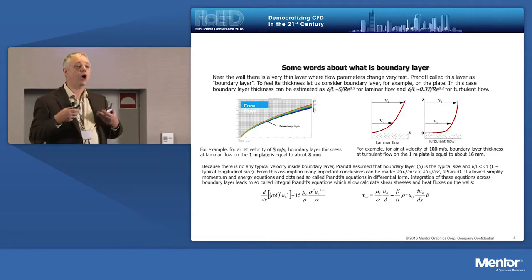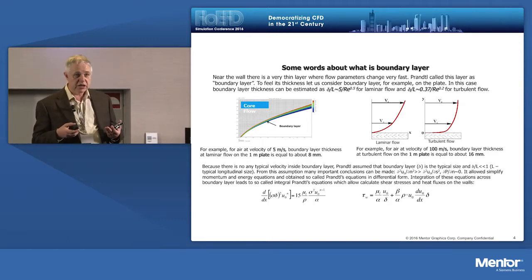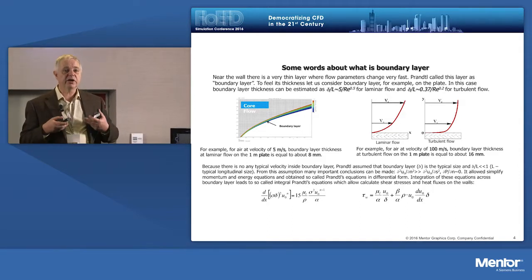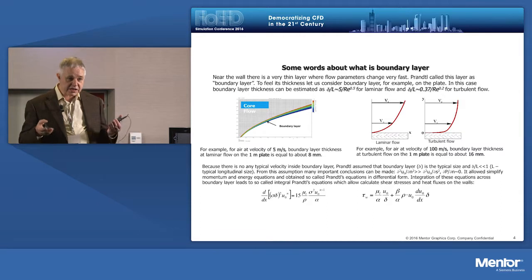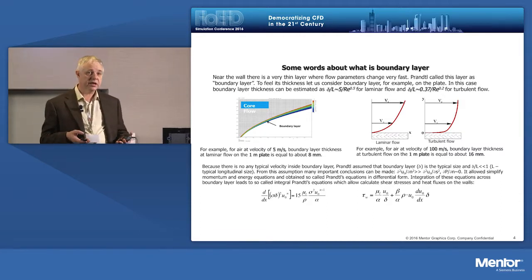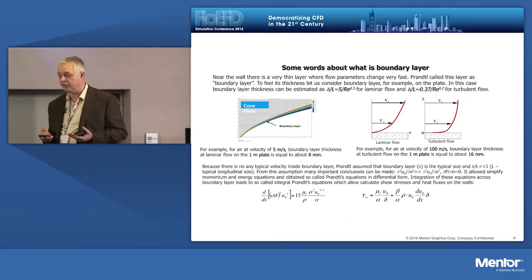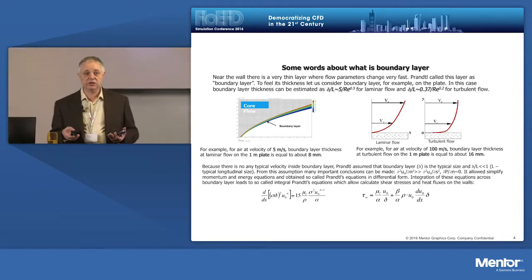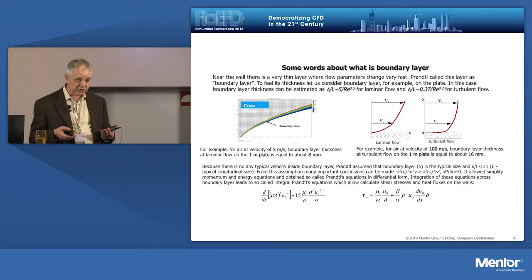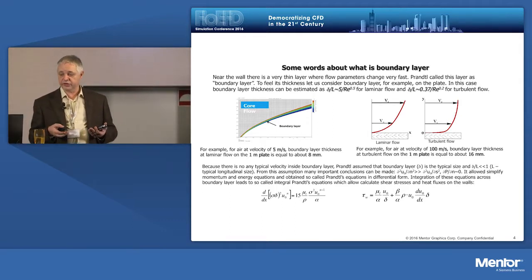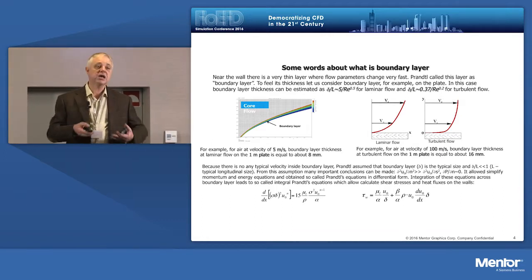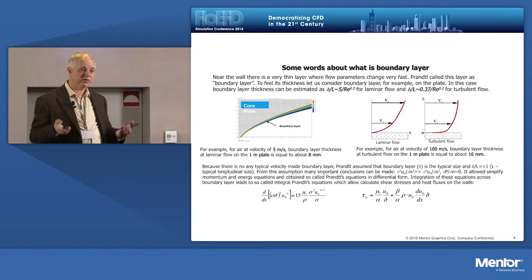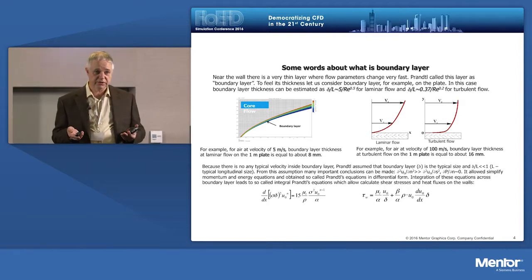Small value, but all physical phenomena which are responsible for shear stresses and heat fluxes are exactly in this boundary layer. And if you have a significant mistake in calculation of the parameters of the boundary layer, then you will achieve nothing. And then it starts. For good resolution of the boundary layer, you need a good mesh, a good computational grid. If the geometry is complicated, the process becomes more and more complicated.